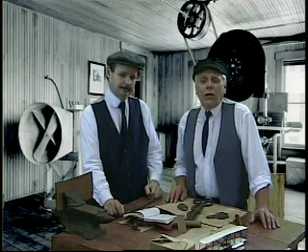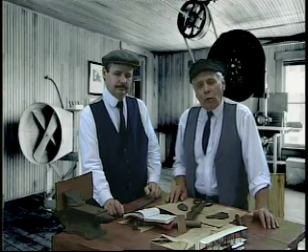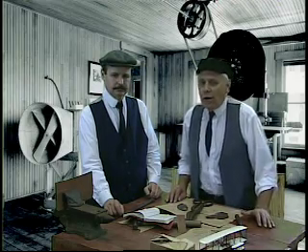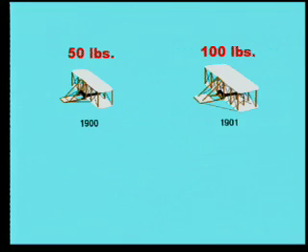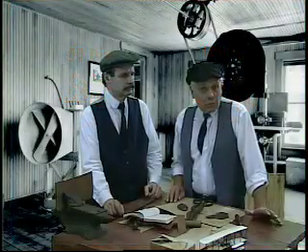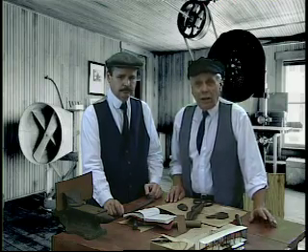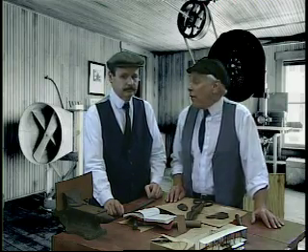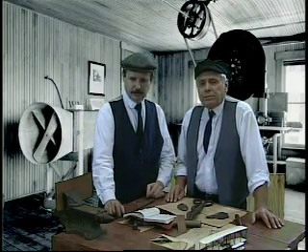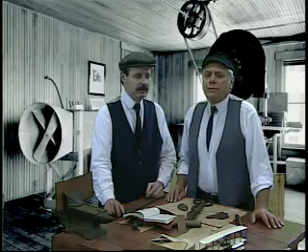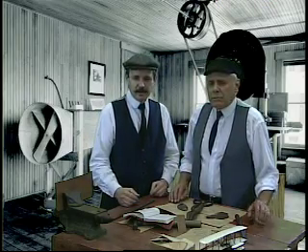Now, using this new value for K, we were able to better calculate the wing area needed for our new 1901 aircraft. The wing area increased from 165 square feet in 1900 to about 290 square feet in 1901. Unfortunately, the weight also increased from about 50 pounds in 1900 to close to 100 pounds in 1901. But both designs were made using the lift equation. That told us how big to make our wing area. Right. We have to say something else about this lift equation. Besides being able to use it to calculate necessary wing area, we made another application.